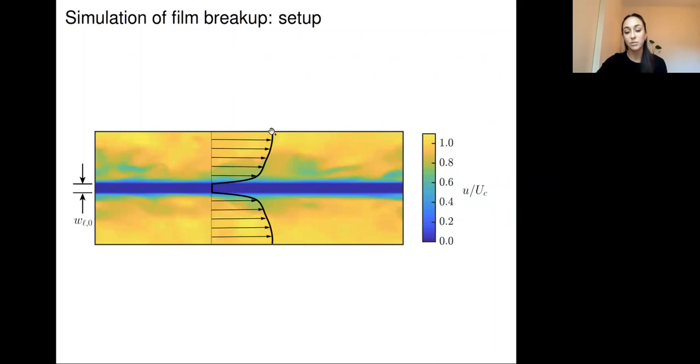And just mindful of what's happening with this shear layer, we see that we've preserved the periodic boundary condition here at the top and bottom. So we haven't violated any rules. And we of course have the periodic boundary conditions still in the streamwise and in the spanwise direction, so out of the page. And we have continuity across this shear layer. So again, this part that was originally at the wall, so zero velocity, is now facing the zero velocity of the film. And so this is a very simple and actually very easy setup to run, and we have minimal moving parts to study this problem in a very fundamental and clean way.